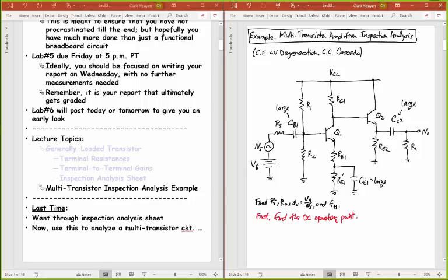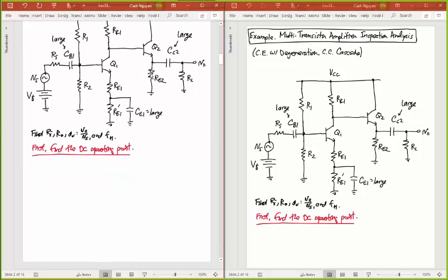Okay, so we first want to find this DC operating point. And how do we go about doing that? Well, you pretty much know how to do that. Let me move on to this side here. Give myself space. And so what you want to do is get all the DC voltages at each of these nodes. And especially you want to get the currents going through these transistors. So arguably the main thing you want to get is the current going through these transistors when we're doing small signal analysis. But as you're learning from your lab, you need to know these DC points as well, because that determines your swing out here. It'll determine how big this capacitor is right there. All sorts of things it determines. And so let's go ahead and do this.